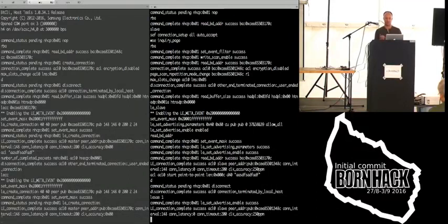Also, as I said, in classic Bluetooth there's this scheme where you and the master can trade places, so you become the master. There's nothing like this in LE, but if these guys wanted to do a role switch, it's much simpler to just disconnect and let the other guy do an advertisement, and then you connect back to him because it's just so fast. In classic Bluetooth there are complicated rules for doing role switches.